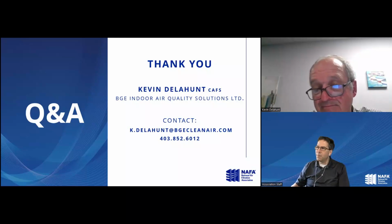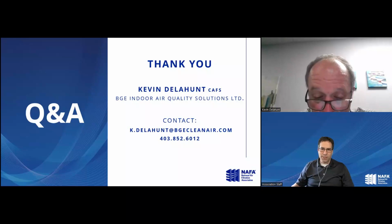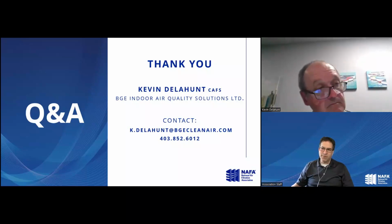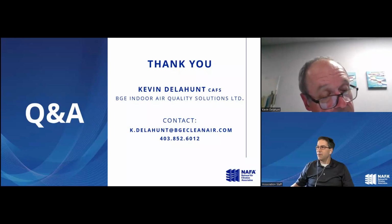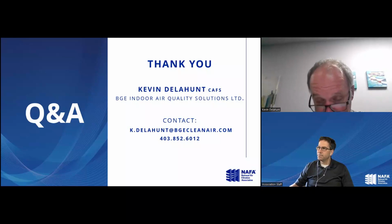Okay, so there's a couple of questions that seem to be related here. I'll ask two questions in a row here, and I think they've got some dots connected. So is it just splitting hairs between MERV 10 and MERV 11 pleat? The other question is, what's your true assessment of using MERV 10 versus MERV 8 pleated filter? Again, it all comes back to what I'm trying to stop. If I look at that one slide with the MERV 6, the MERV 11, the MERV 13, and the HEPA filter, what am I willing to allow to penetrate my occupied space?